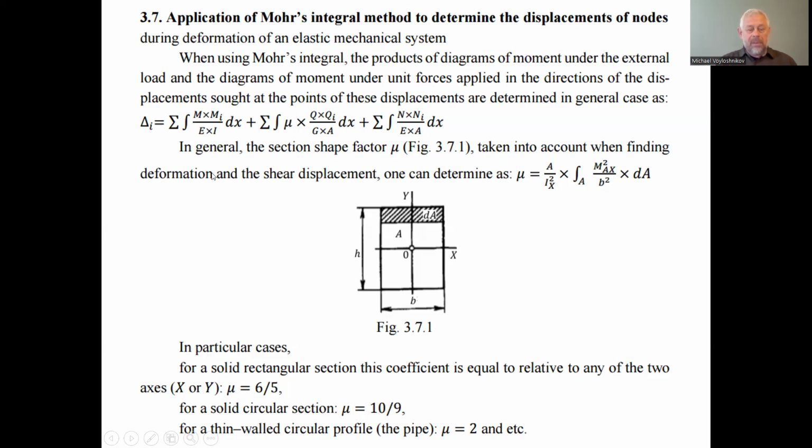In the general approach, we can indicate the Mohr integral as consisting of three summands for the flat state. For the state in space, we can consider the Mohr integral consisting of 6 summands. It depends on the number of directions in space and on the plane. So the Mohr integral consists of 3 summands in the considered case, and the first summand is a total of integrals.